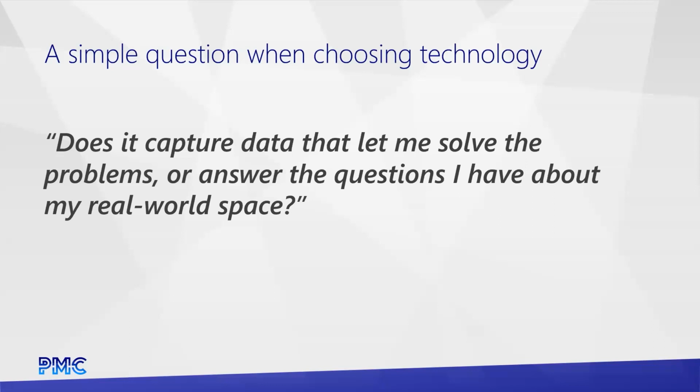Right. So if you have a very small space and your dimensional requirements are pretty simple, Matterport might be your best choice, right? It's going to be very cheap to execute. We're going to be able to do it very quickly. But if your capture is 100,000 square foot manufacturing space, I would definitely not recommend Matterport. So we want to make sure that we align the equipment choice with how the data is actually going to be used.